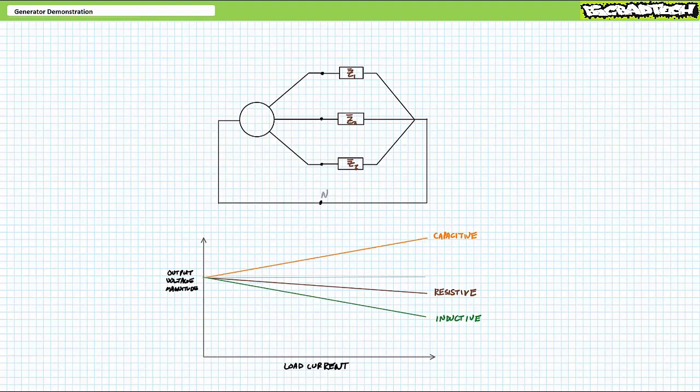Again, I need to remind you that part 1 of this demonstration made use of a prime mover utilizing closed-loop speed control and explored load-induced output voltage magnitude variation only and did not explore load-induced frequency variation. Viewers will note every time the generator encountered an increased demand in real power, i.e. primarily resistive components, and the very small non-ideal components of real-world inductors and capacitors, the generator consumed more mechanical power from the prime mover. Given the prime mover was in constant speed mode, it responded with increased torque to keep speed constant. Which brings us to part 2.